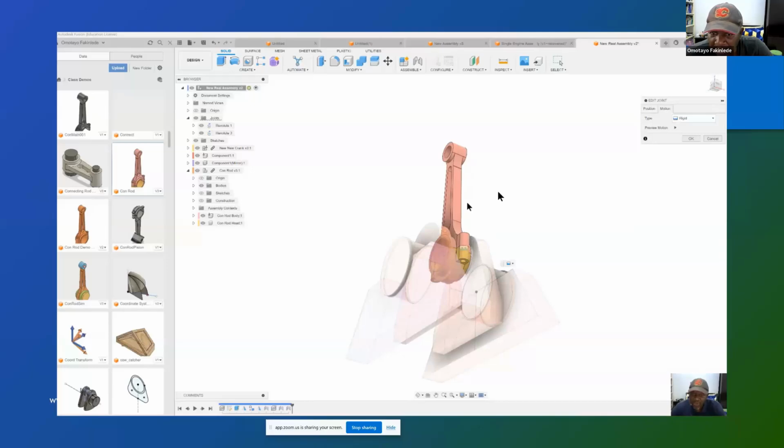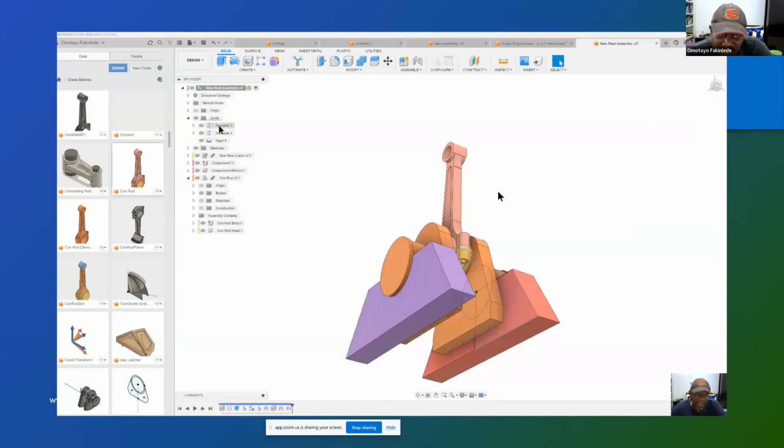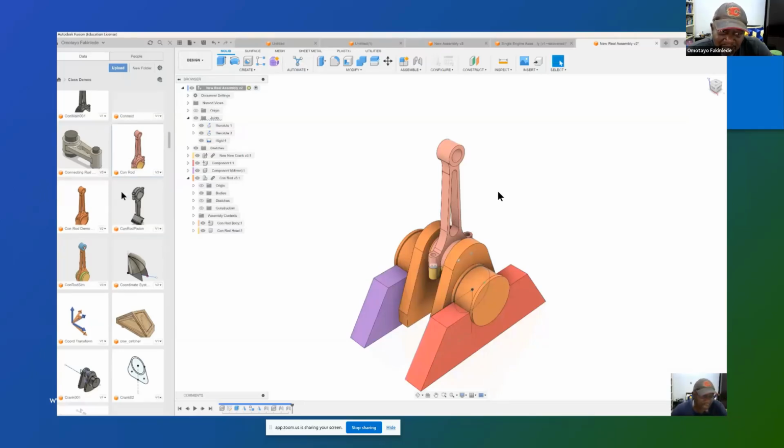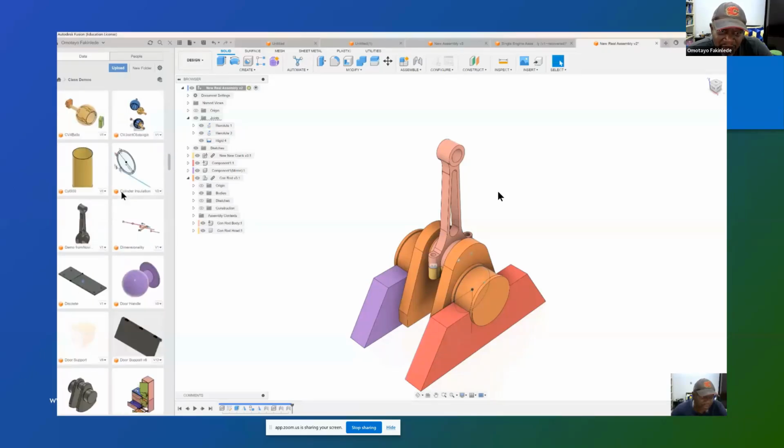Okay, so that shows the head at the bottom of the head and body of the connecting rod joint. So it's now rigid motion, not revolute. So we can now test the revolute 3. That's revolute motion again. So we can go and click it and test it. If we test it, we'll see that it carries the whole thing with itself.